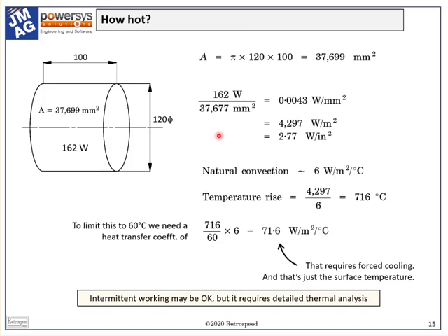We've said that this motor might be running hot. Let's see a little more detail. All we've done is to work with a high current density of 12 amps per square millimeter, and although we have also noted that the core losses may be high as well, we haven't actually calculated them. So what we're looking at here may be somewhat optimistic.